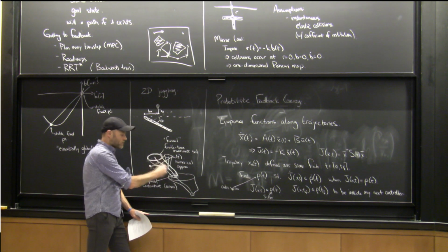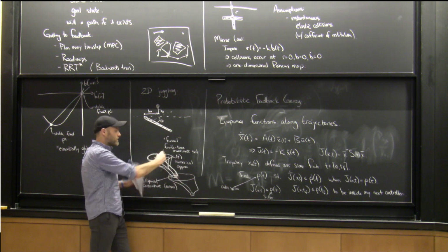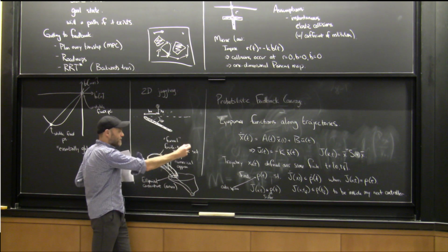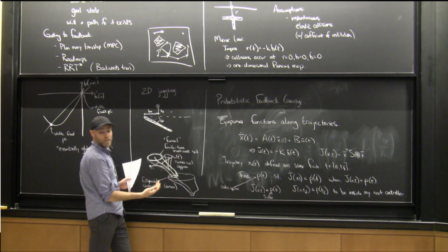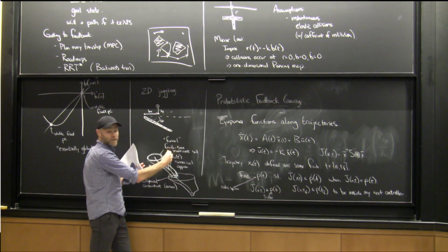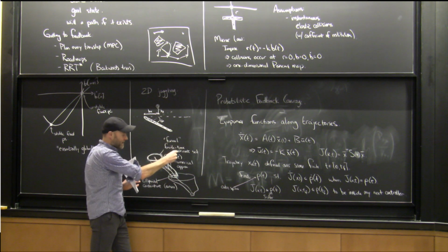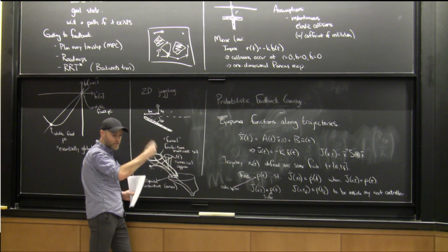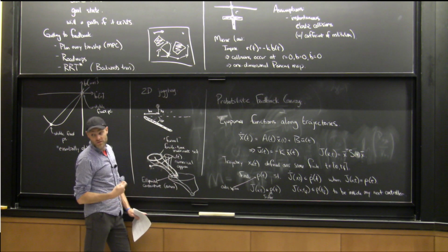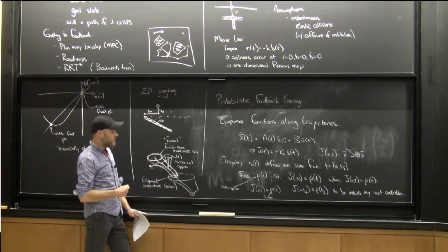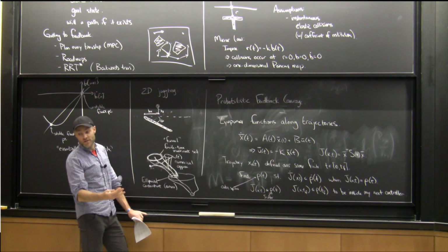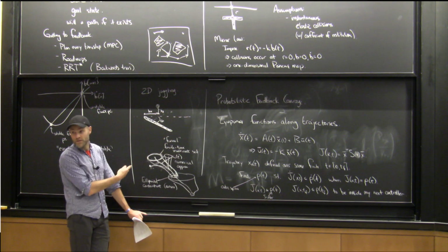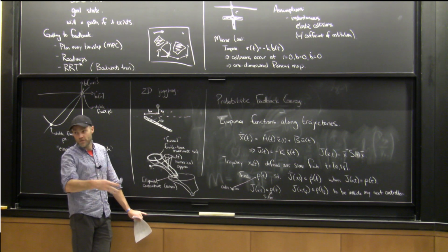That I add a trajectory. I assume its funnel is infinite. Every time I go to start a new execution, I pick the funnel that I'm inside. I start executing it. If it lied to me and I failed, then I crop the funnel. Right, and then I add a new trajectory to do it, and I can sort of iteratively on the fly build these things with a simulation-based version, and that has appeal for being out in the wild. And every time I've experienced a new trajectory which falsified my previous controller, I make it better, and it just keeps improving.